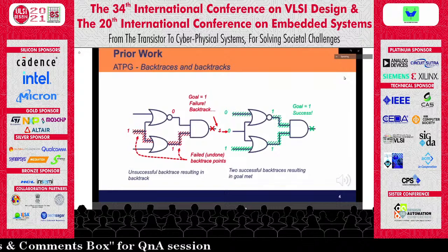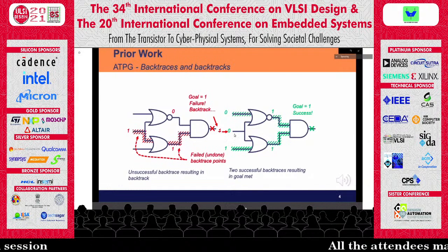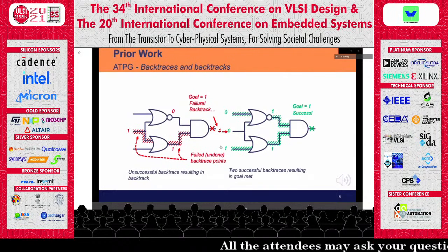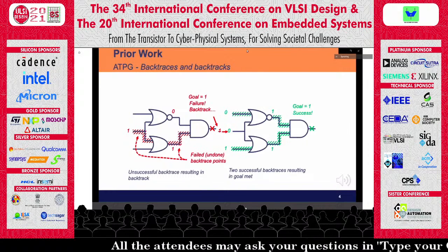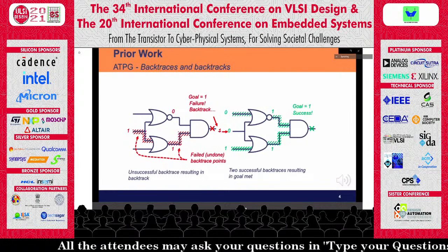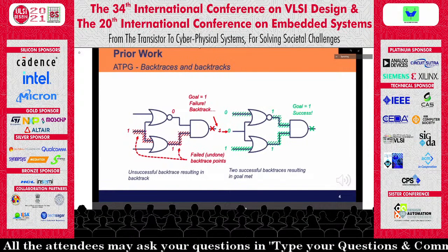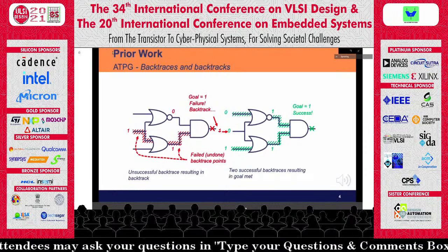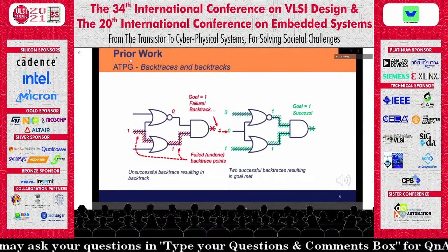When this occurs, ATPG must undo or backtrack to some previous assignment, which means ATPG wastes time simulating unnecessary input vectors. Beyond PODEM, numerous ATPG algorithms attempt to reduce runtime by creating fewer objectives, but to our knowledge, no studies compare ways of backtracing from an objective. When backtracing, it must decide which direction to go, but choosing a wrong direction may result in a backtrack.